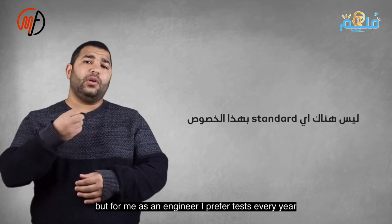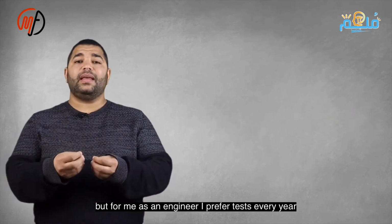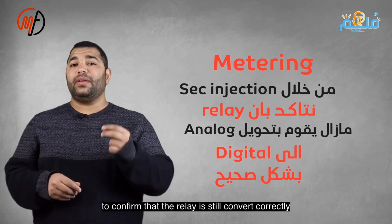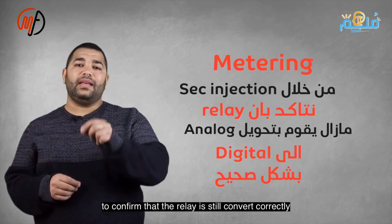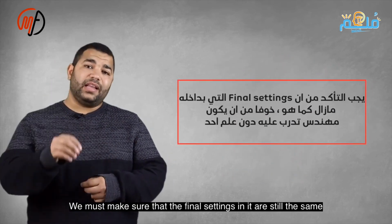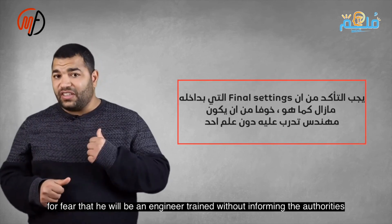These annual tests include checking the metering to ensure that the relay is still converting the analog signals correctly. It's also important to verify that the internal components remain unchanged, to ensure that no engineer has come during this period to work on the relay without anyone's knowledge or permission. It's also preferable to pull the event record data and analyze it to check if anything unusual occurred during this period. If it's not possible to conduct maintenance tests annually, a schedule can be created that includes all network protections, which is agreed upon internally.